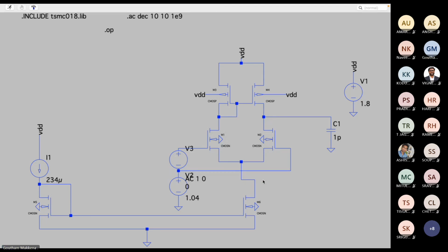VDS and VGS. But this is more prone to the variations in VDS, right? Because at the end of the day, these two act like source followers, and whatever is the variation here, it comes over here as the average of these two. Yes or no? We have seen in the morning V1 plus V2 by 2. Yes or no? Yes. Okay, so this node is prone to a lot of variations from the input side.